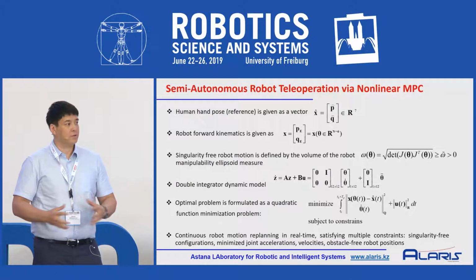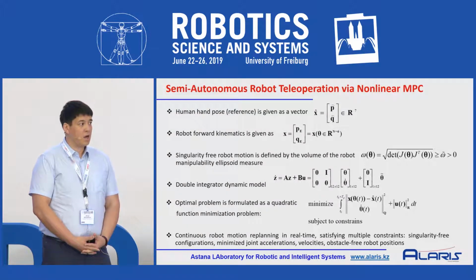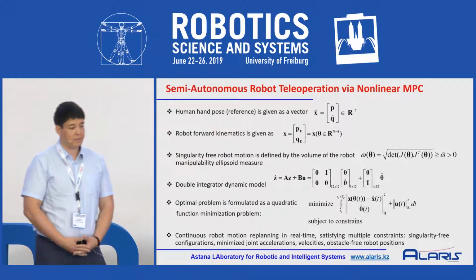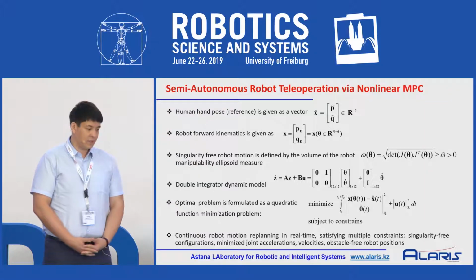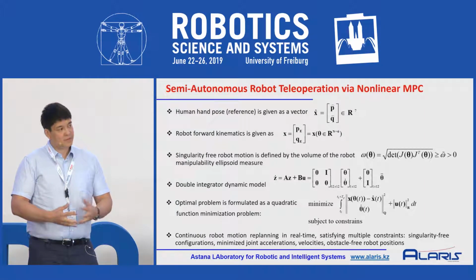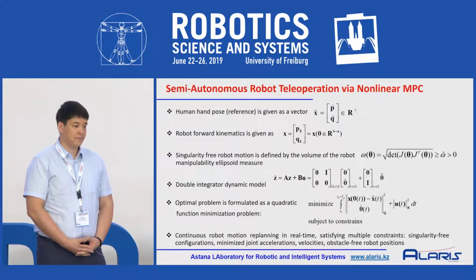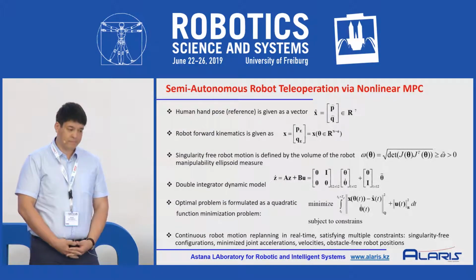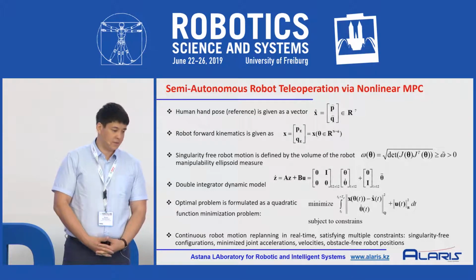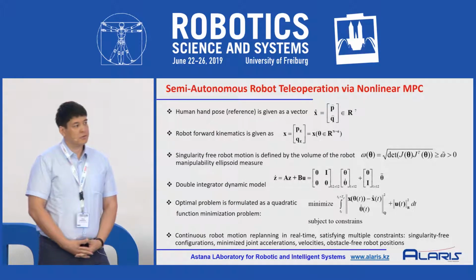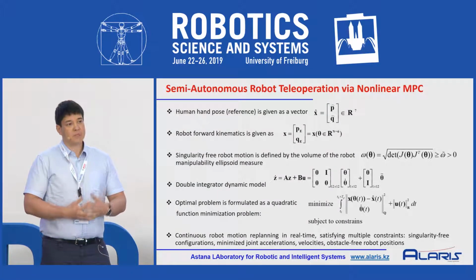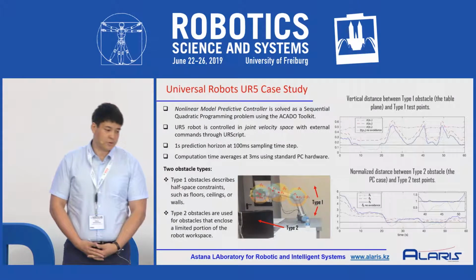We formulate our arm motion using quaternion algebra, for orientation and position, and the optimization problem we defined as minimizing the error between the human hand motion and the robot end effector position and orientation, and we also minimize joint velocities to generate smooth real-time robot motion.